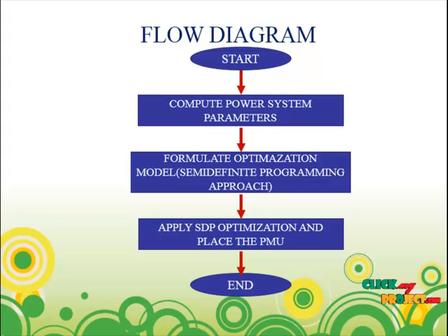The phasor data concentrator aligns information by time, the incoming PMU messages from multiple measuring devices, and sends out the aggregated synchronized data set as a single data stream. It archives data and processes the information, exchanging records with PDCs at other locations. Communication links multiple PMUs to a PDC that links multiple sources, and the captured phasors are to be time tagged based on the UTC time reference. The SOC time counts the number of seconds that have occurred since the epoch.